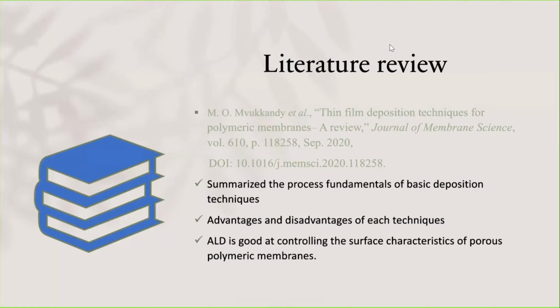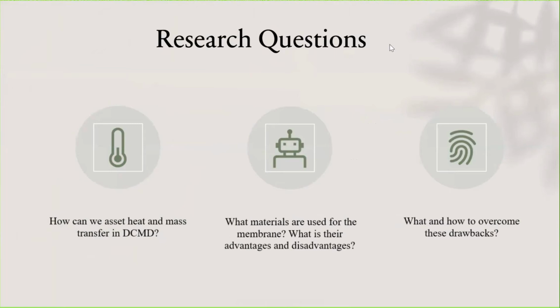They stated that PVD techniques are commonly beneficial due to their low cost, ease of use, and scalability. E-beam evaporation is more flexible than thermal evaporation. ALD is effective at changing the surface property of porous polymer membranes, and it's also useful for balancing membrane permeability and selectivity.